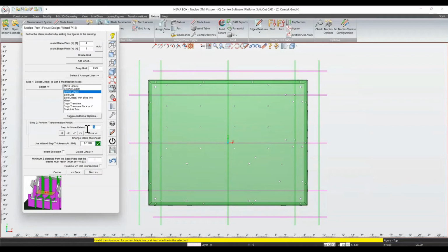We can do the shrink. Come over here. It was 2. And then we do the positive side here. And then we can go to a 0.5 again, just to get that same amount over here. Next, what we'll do is we'll do these green ones, and those will be in the Y positive negative. So let's go 2.5, and then we'll go negative. Looks good. Positive. Looks good. So that pulls back away from the corners for each of these.